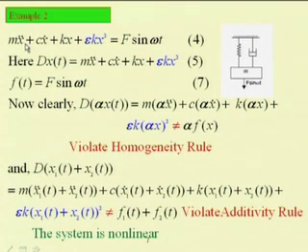In all these cases, for example, in the spring mass system, when I put x dot, or the time derivative of the displacement, equal to 0, I can find this kx for this linear system. Consider this linear system m x double dot plus c x dot plus k x equal to 0 for free vibration. If I put x dot and x double dot equal to 0, then the resulting value becomes kx equal to 0. So x equal to 0. So x equal to 0 represents the equilibrium position.